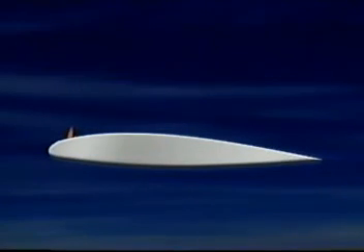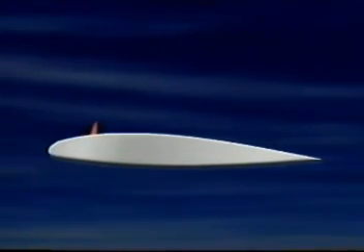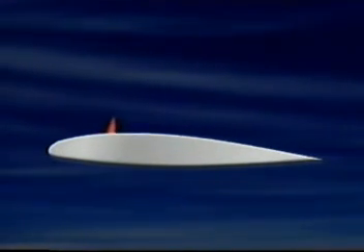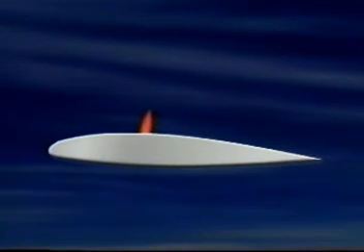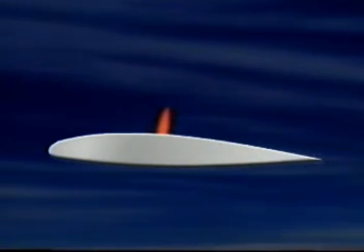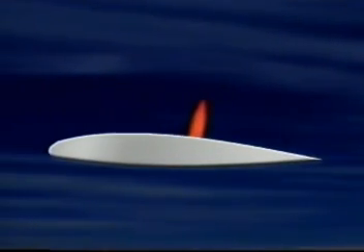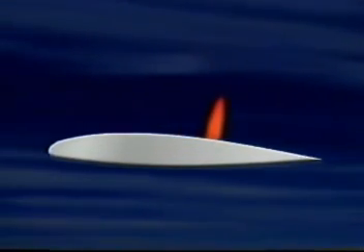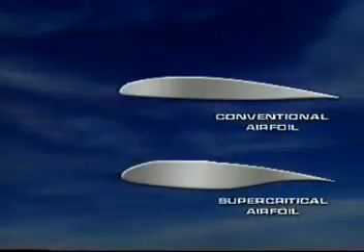If speed is further increased above the critical Mach number, drag increases drastically. Buffeting is felt. Then the aircraft may suffer from certain stability and control deficiencies. The common sense signals that the jet should fly at the highest subsonic speed before compressibility effects, the shock wave we have mentioned, appear or become excessive. The exponential increase in drag must be solved with aerodynamic resources and design measures if we want to fly fast.